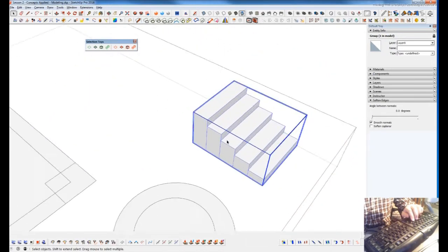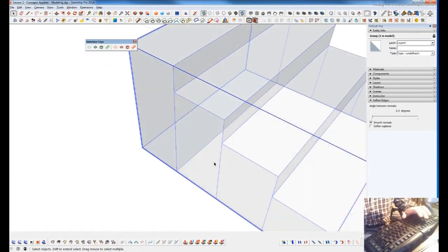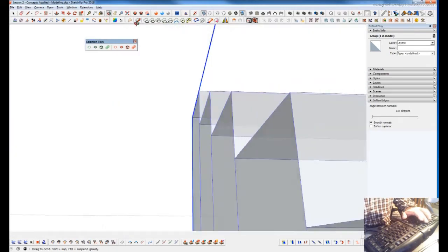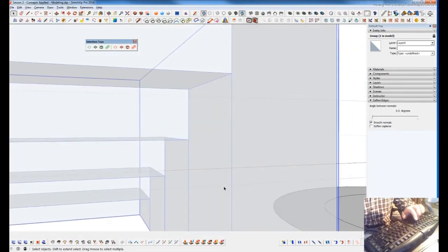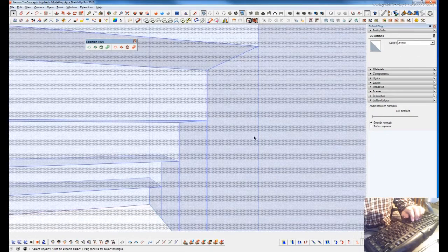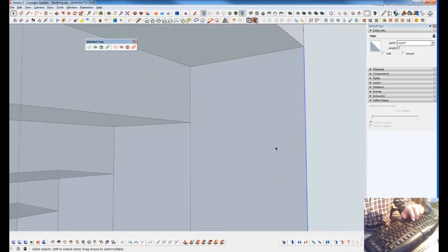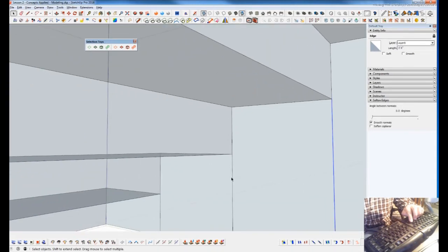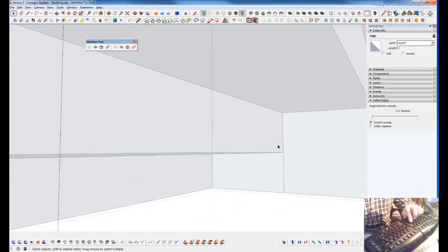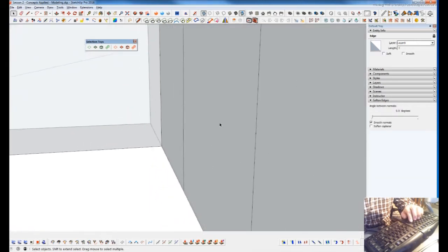It works in a variety of situations. It will go through, and if I turn on X-ray mode, let's see, there's no inner edges there right now. But I'm going to get inside of here, and I'm just going to do my Control-Alt-G. Now I've made a face there. Select this edge, do that Generate Faces shortcut. Selected and generated another one.